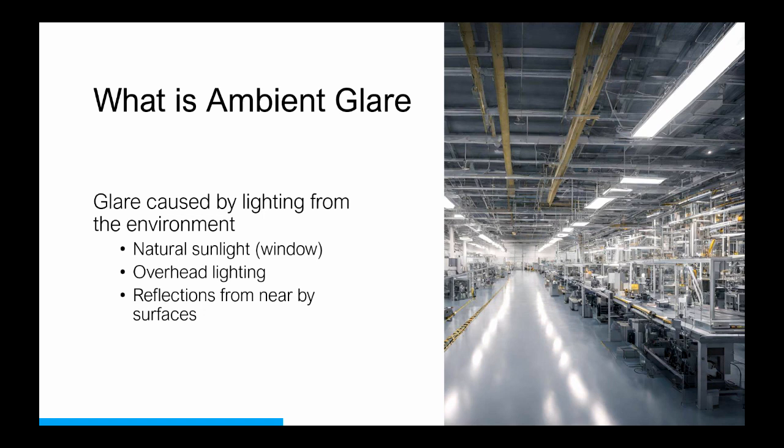Sometimes it's just a natural window, if there's sunlight coming through, and this one is extra fun because on Tuesday, it's cloudy outside, you don't have a problem, everything goes great. But Thursday, it's a really beautiful, bright, sunny day, and now your machine vision system isn't working. And if you're not aware of the glare problem, you're not really sure why it works on Tuesdays but doesn't work on Thursdays. That creates a headache as well. So natural windows nearby always can be a problem.